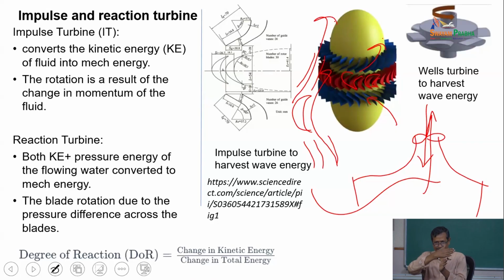When it is hitting, the air is changing direction, and when it changes direction it gives some energy to the turbine blade. When it gives energy, the blade gets force, so it will try to rotate. So, air is blowing, the guide vane gives the angle, then it hits the crescent shaped blade which gets energy. Then when the air exits the blade, it goes through another guide vane and exits. The air passing through the guide vane does not give energy, but it gives proper direction so that the blade can be hit properly.